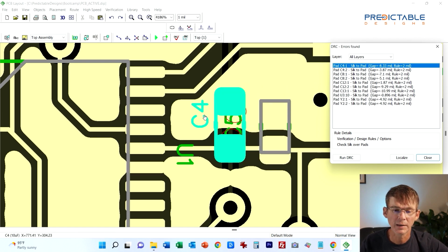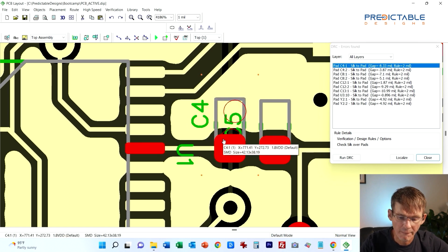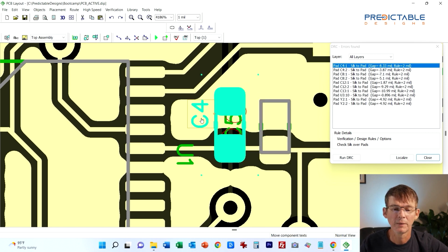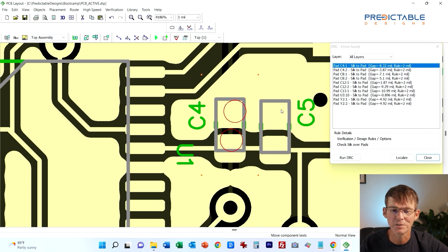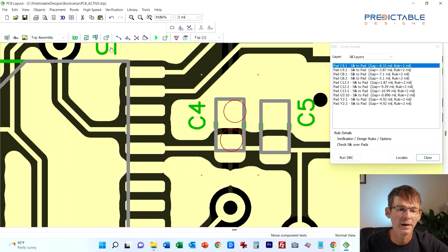and now I can, there we go. Okay, now I just move around the reference designator without moving the device. This C4 one's okay. It's C5 that's a problem. So let's move it over here because this is really C5 here. This is C4. This U1's not a problem where it's at, but it's for this chip here. So I would move it up here, and it's kind of in a random spot here. So I'm going to just right click on that, rotate it around, and move that up here.